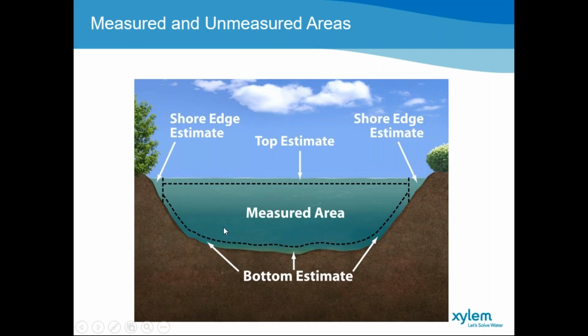The edges are basically limited to the minimum depth the acoustic Doppler instrument can measure. The international standards requirement for edge measurements is that you are able to collect a depth where you have 2 valid cells, and then 10 samples or ensembles are measured at that specific location and averaged to extrapolate towards the water edge.